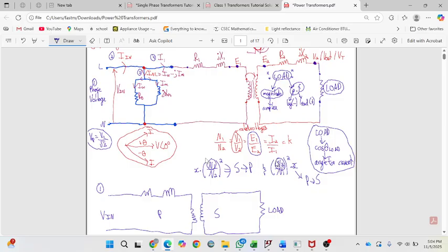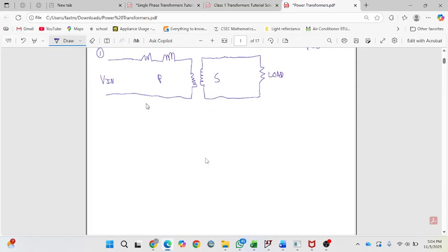The whole equation itself is kind of the same. So let's run through it. If I go from the secondary to the primary, I'll just do one so you can understand the concept. You'll have R2 prime, because it's not R2 anymore. It'll be R2 multiplied by N1 on N2, squared, since you go into the primary side.